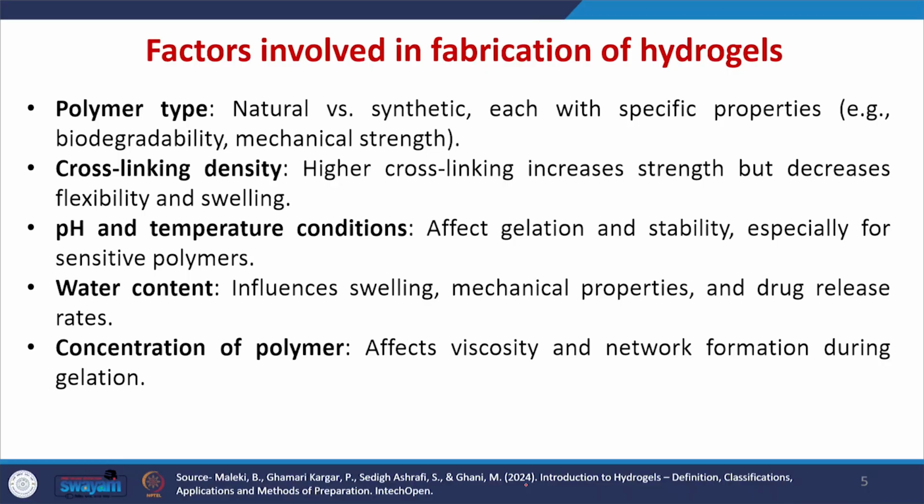Let us see the factors involved in fabrication of hydrogels. The first one is polymer type. It can be a natural or synthetic polymer, depending on your final application. We have to select the polymer. If you want to go for a biodegradable scaffold, we can go for a natural polymer, and if you want more mechanical strength, and it has to stay for a long time, we can go for a synthetic polymer.